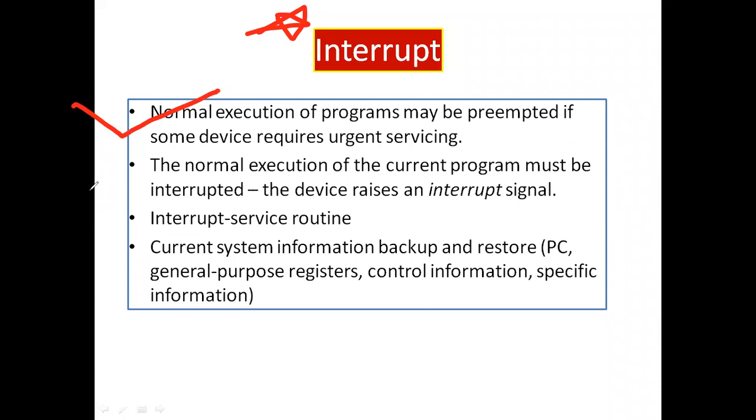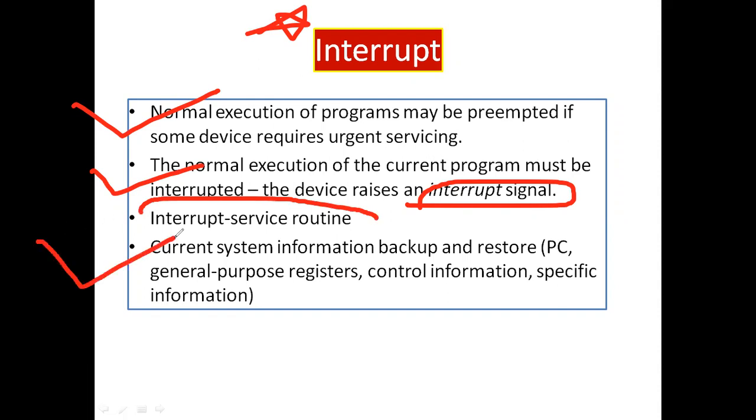The normal execution of the current program must be interrupted, and for that the device raises an interrupt signal. To deal with that interrupt, a service routine is there. Current system information is backed up and restored: PC, general purpose registers, control information and so on.